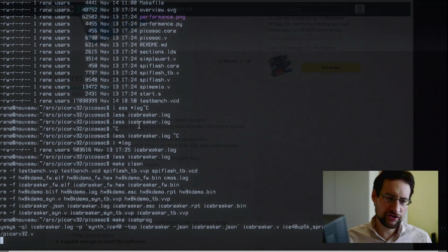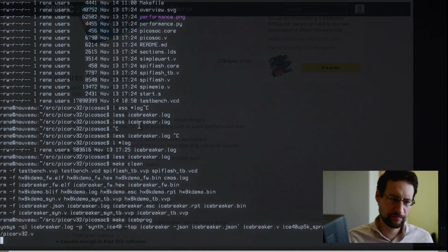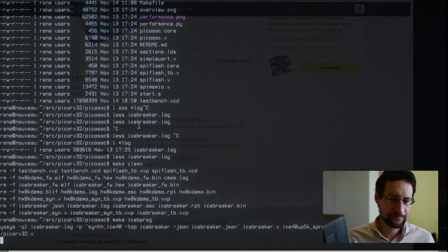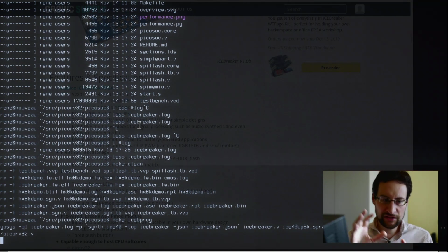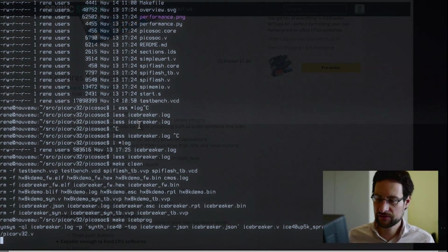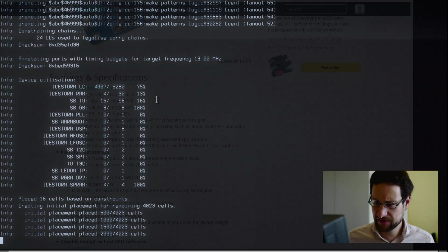And so the challenge is how many logic elements we have left, because quite some are taken by the RISC-V core, and I think the HDMI output example had some 800 logic elements used to output these moving lines and balls. And of course we can delete most of this. We delete the lines and we delete the moving ball. That frees some logic elements, certainly, but we will need much more. So the challenge is, I was thinking to, a little bit like the 8-Bit Guy, create here some homebrew system. Of course now the synthesis is running.